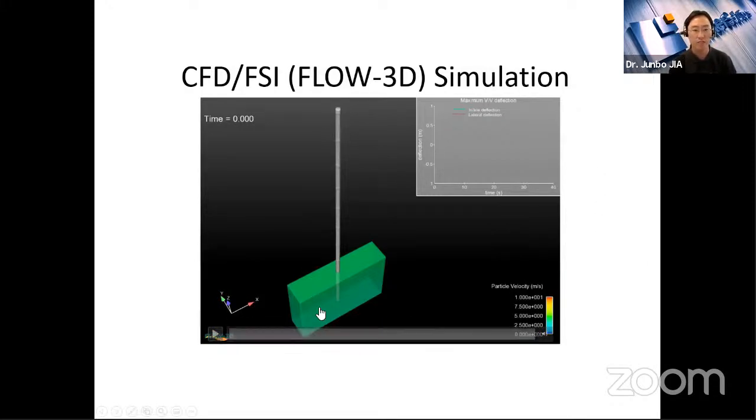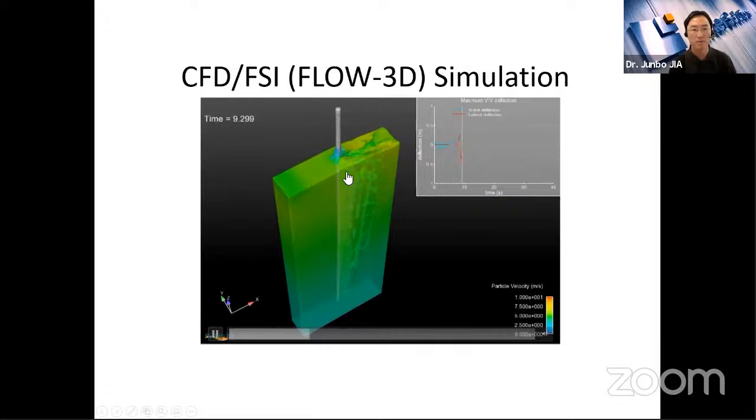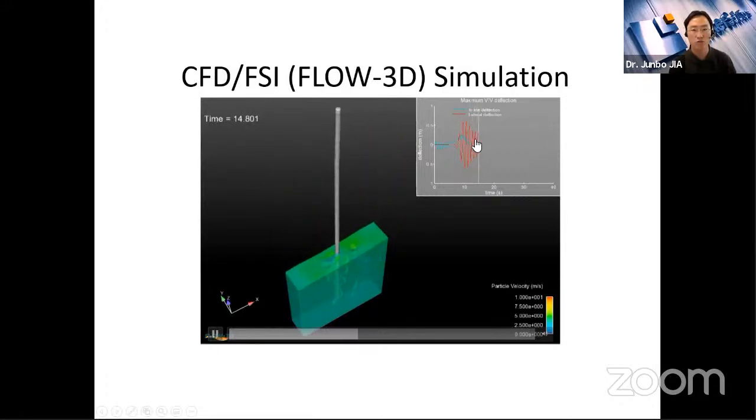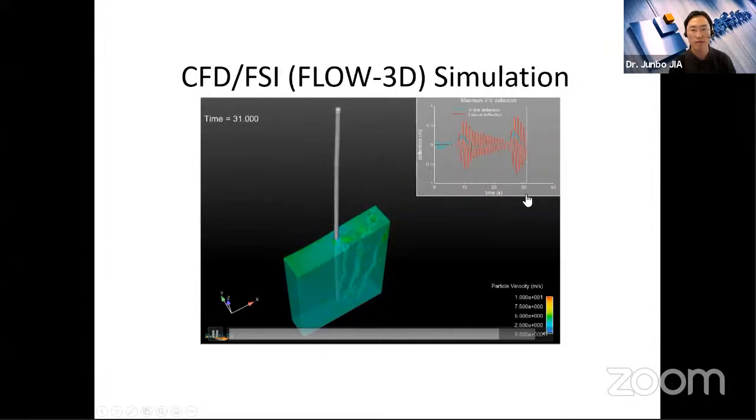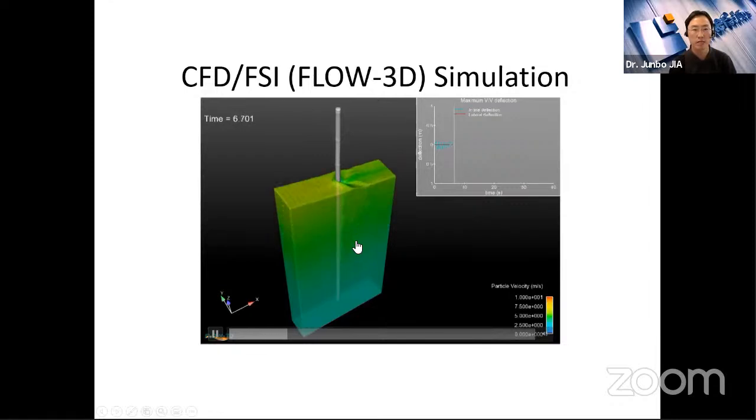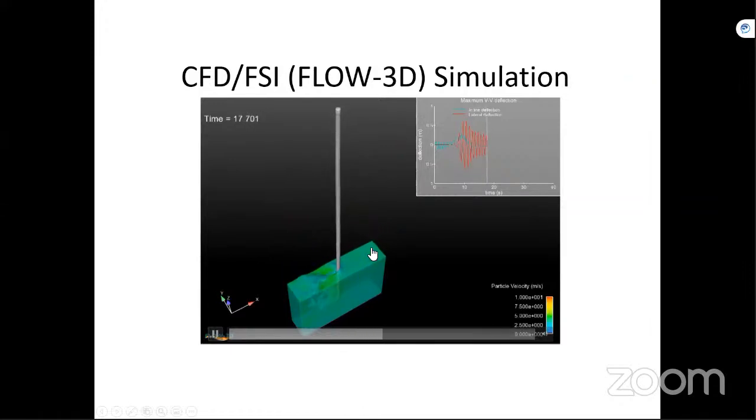So this is one of our designs, trying to see a submerged piping, technically we call that a riser system, and how it interacts with the subsea current and waves. So you will see the simulation, and it actually shows some resonance vibration. If you see this red line, after some cycles of wave and current loading, it increases its amplitude dramatically due to the resonance vibration. So that's what causes the problem for our subsea riser design, and we have to treat that very, very carefully.